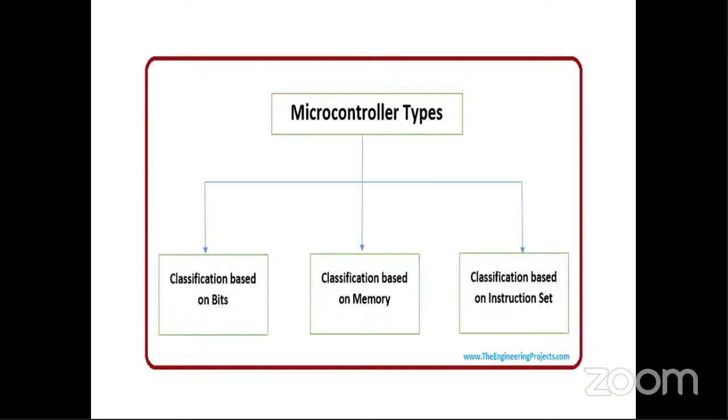Another type on which you can categorize microcontrollers is Harvard architecture, or Princeton architecture. Princeton is known as von Neumann architecture. In this von Neumann architecture, as we know, each microcontroller has inbuilt memory in it. So memory consists of ROM as well as RAM. In Princeton architecture, the program memory and data memory are stored in a single chip. So the data and the codes, that is your operands and opcodes, are stored together, and it has only one address bus and data bus.